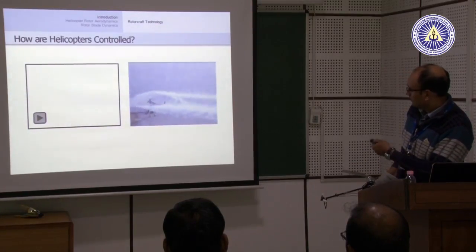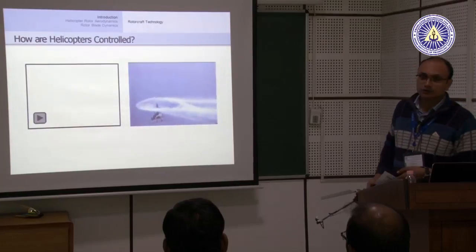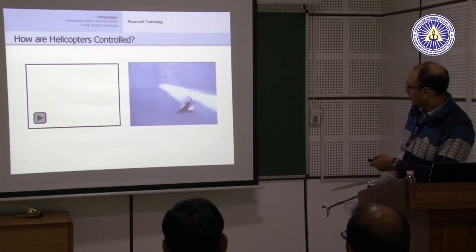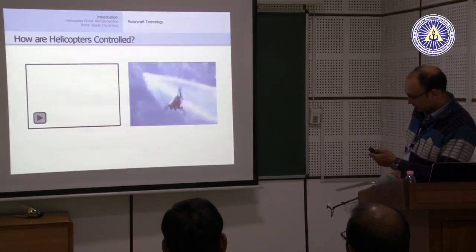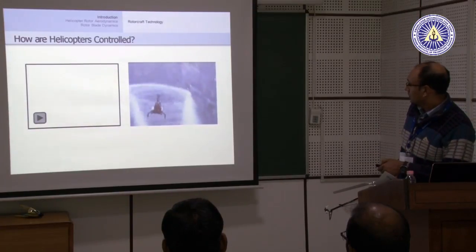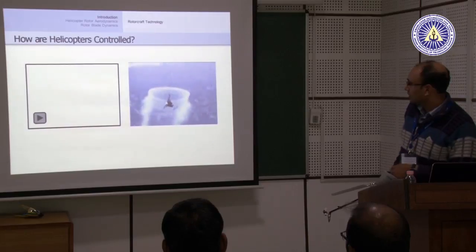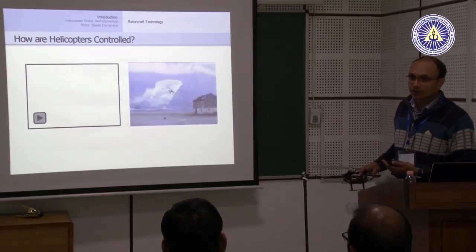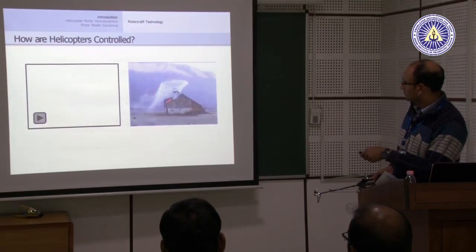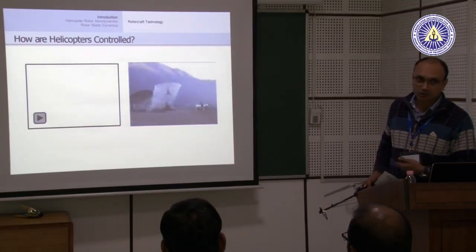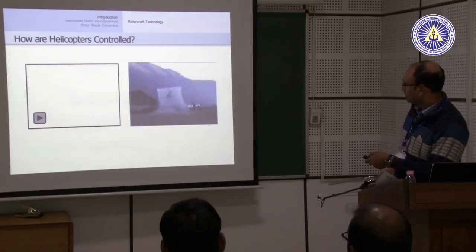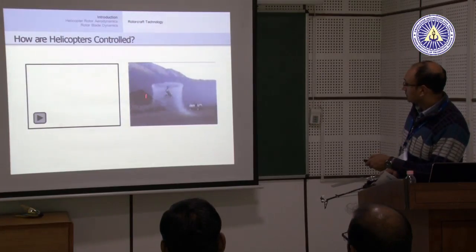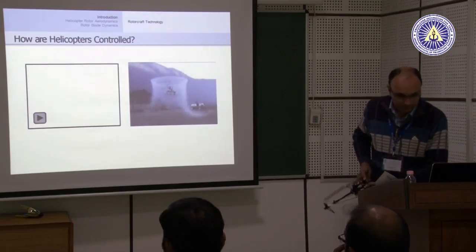So, this actually gives a very nice visualization of the flow around the rotor. In forward flight, the rotor behaves quite a bit like a circular wing. If you look at the flow field of a wing, you will see vortices near the edge of the rotor, which are called tip vortices. And here, even in hovering flight, the wake is convected nicely downwards.